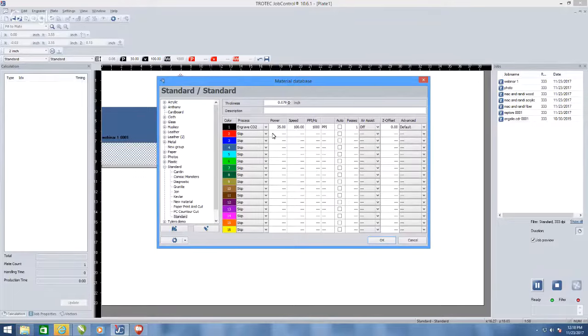When I look at vector engraving, let's say I'm cutting and I say I want to use 3. That's 3% of 140 inches a second. So basically you would take 3% of 140, and you would have maybe about 4 inches per second. If I go down to 2, then you're less. Down to 1, we're even less. So we're using a percentage of 140 inches per second.